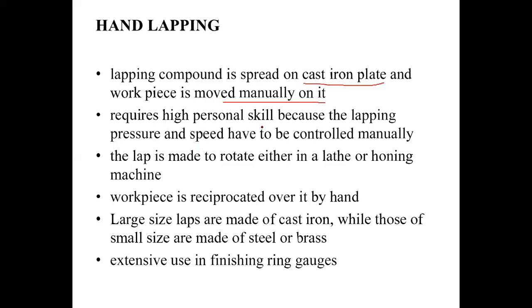Hand lapping requires high personal skill, because you are doing it manually. The pressure and speed have to be controlled manually, so experience is needed. In your MMT, when you were polishing, you may have seen that if polishing is not done properly, your surface does not come flat. You get an inclined surface. Similarly here, if you do not hold it properly, or do not control the proper speed and orientation, your surface may not come smooth and may become inclined. That is why in hand lapping, the skill of the operator is very important.